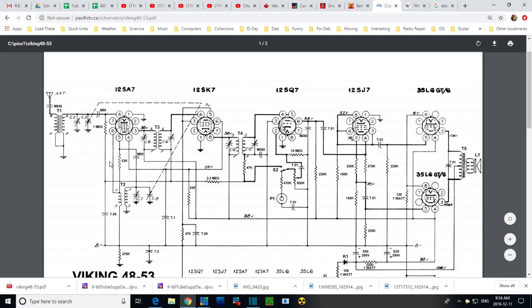The last little AM radio I did has another tube out here before the mixer tube. And that creates the ability to sharpen the filtering. You could pretty much call it filtering out here. Sometimes this is called the pre-selector circuit, where you're trying to select the signal you want to present to the mixer tube.